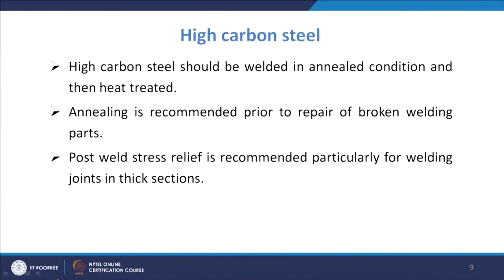When we are talking about high carbon steel welding, normally they should be welded in the annealed condition and then heat treated. That is suggested, because then the likelihood of cracking or undesirable effects is less.